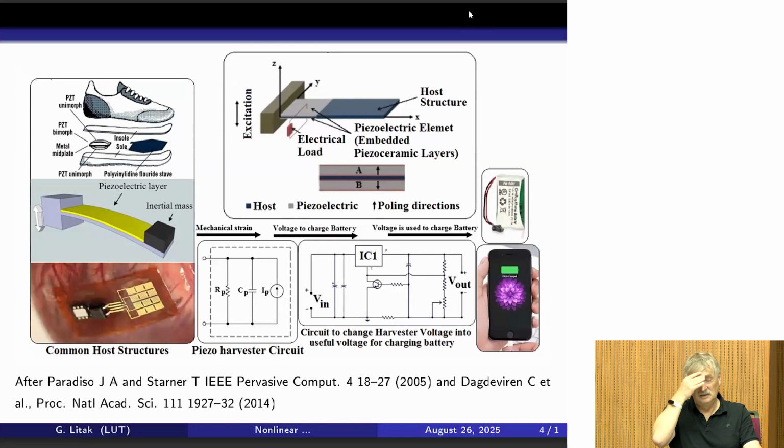This is again some introduction to energy harvesting. You see that we are not going to have a large amount of energy. So we are thinking about powering small sensors or small electronic devices, and the most useful device is composed of piezoelectric material. It could also be electromagnetic. However, there is not such a possibility of scaling electromagnetic, so you need more space.